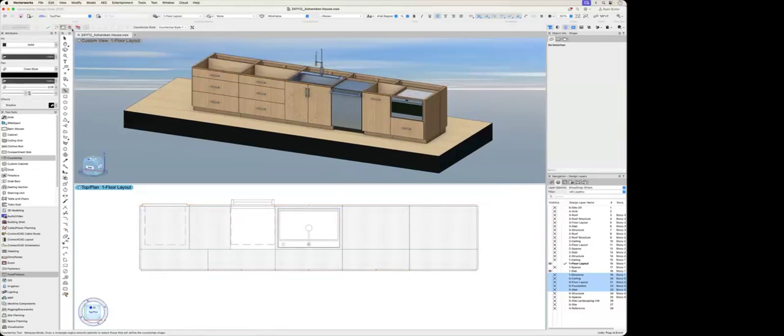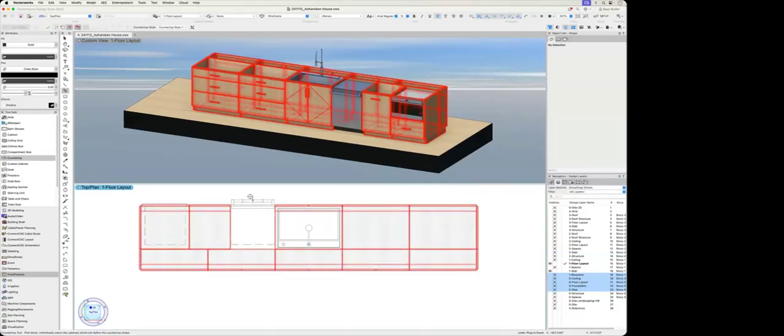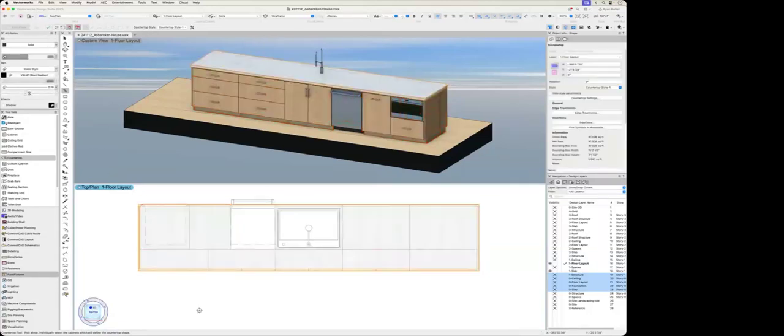Now the last one, which is my favorite one, is the pick mode. The pick mode is really great because you choose which cabinets you want here. So if I'm rolling over the cabinets, you could see that they're highlighting. And then also there's a bridge mode. Now the bridge mode, when this is enabled, it will gap over certain areas. Like for example, this area here where the dishwasher is, if I select all these cabinets, I don't have a cabinet selected here, but it will bridge over that to make a countertop. Like that. So that's really great and very easy to do when you are creating a countertop.